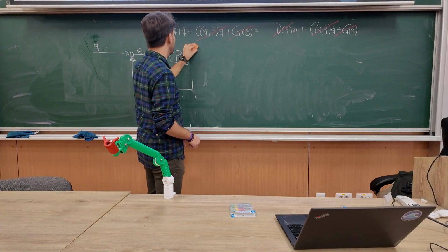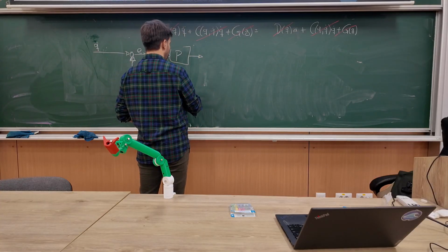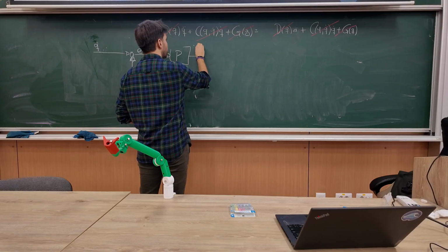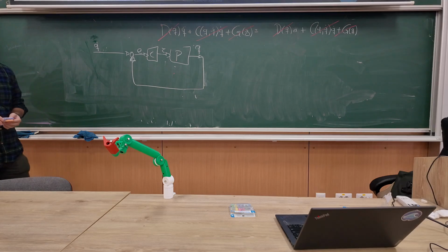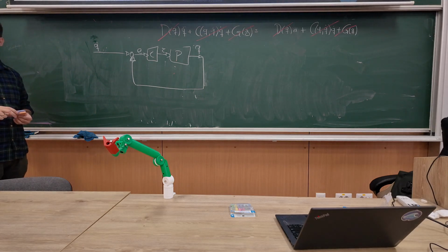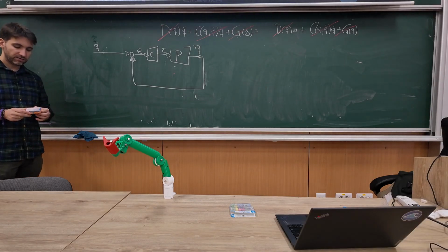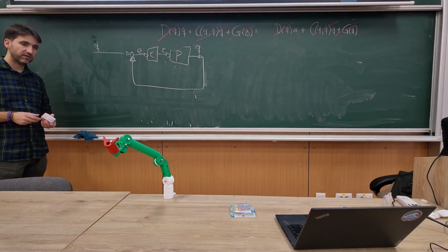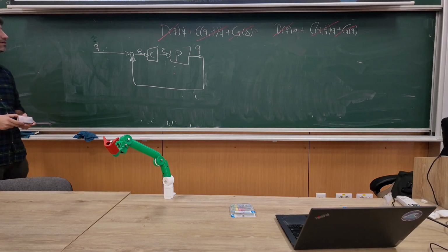So what do I need to do in order to control the end effector velocity? What blocks do I need? The Jacobian. Yeah, the Jacobian can be calculated with the joint positions. So where do I put it? The Jacobian makes sense because it gives me the relation between joint velocities and end effector velocities, right? So where should I put it?